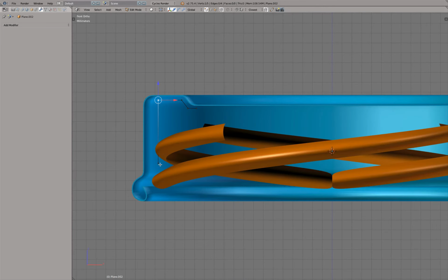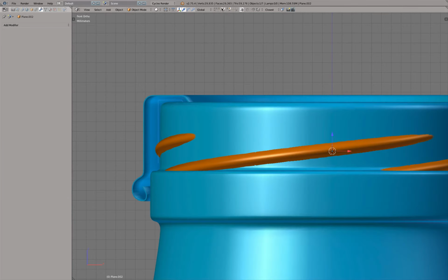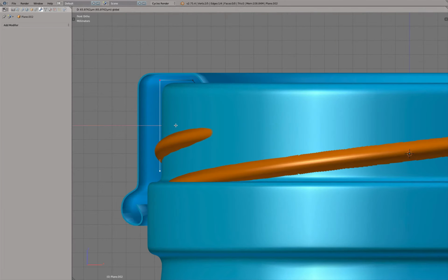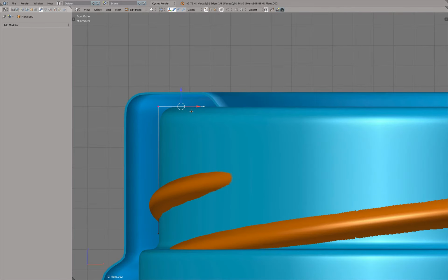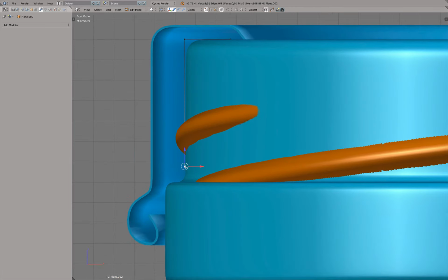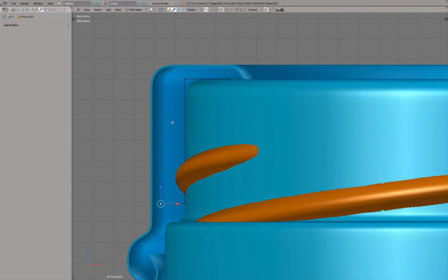And here you see, for example, this line, how much it intersects the threading. So this line probably can be pushed a little bit closer, and this can actually be pushed closer down because that layer will be compressed and it's going to seal the bottle, so no fluid will come out. This one can go up a little bit, maybe to there, and then maybe let's move this one over. Let's move this one up. Actually, this we get really close.